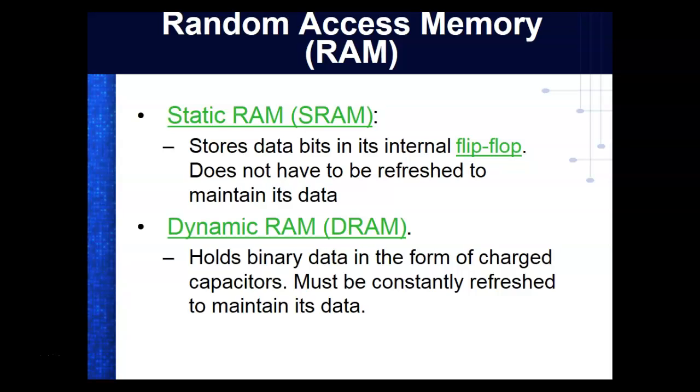But these are what we call volatile memories. Volatile memory means if you turn the power off, everything that's in there is what? Gone. So if I come over here, I turn this computer off, I pull that battery out, anything that's in RAM is gone. It's volatile memory. So RAM is usually volatile memory. But it's short-term memory, so we can very easily do what? Load it back in. We have what we call DRAM. This is probably what's in your computer. This is a lot less expensive. This guy right here, transistor-wise, this guy right here took 6 transistors per storage cell.